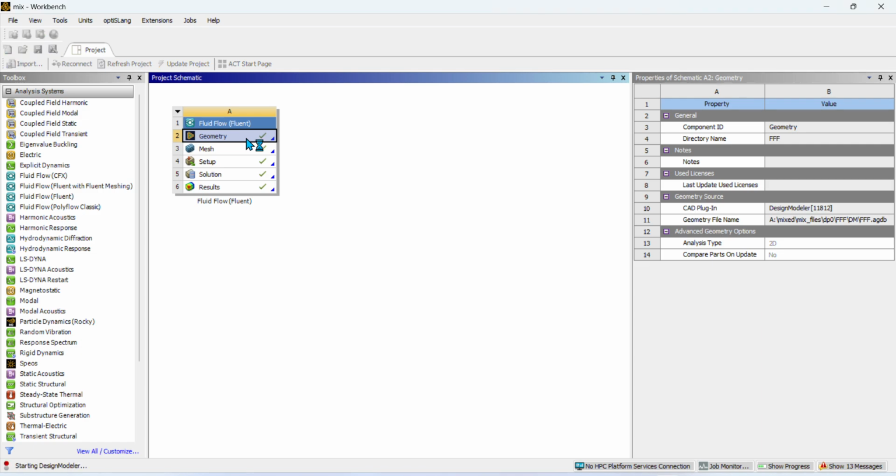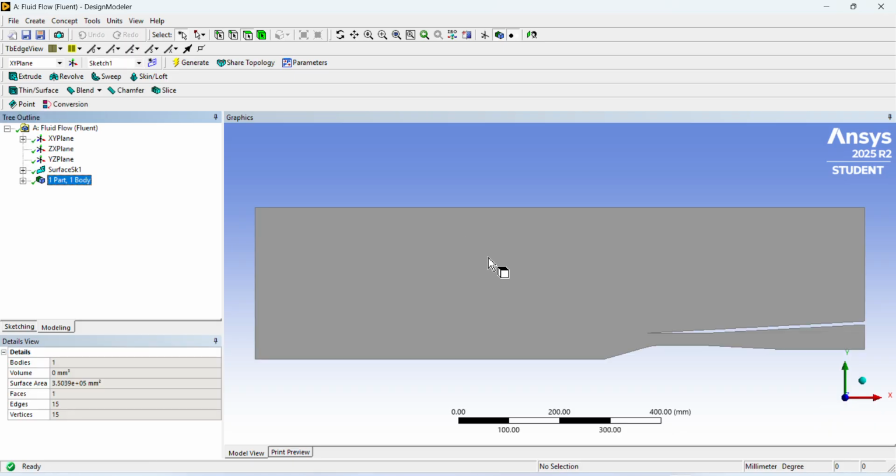Okay, I will cross-check once again with my double bleed hole. Whatever slot I created, the same slot I will create adjacent to my first bleed. Then I will check the pressure recovery for the two bleed system. If it is not optimal, then I will go for a three hole bleeding process.